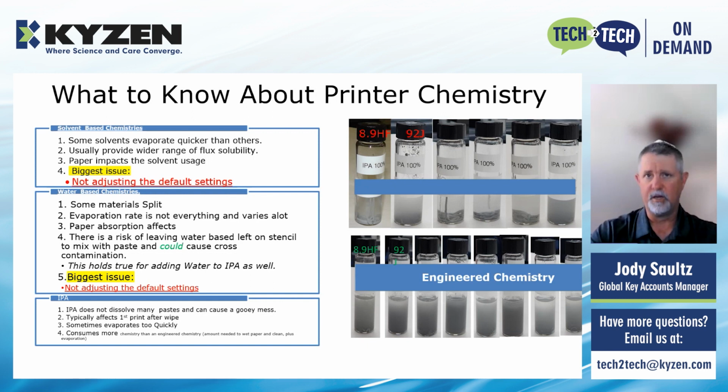So many times I hear customers say, "Oh, we mix water with the IPA." That's probably worse than running IPA at 100%, which I don't recommend anyway. And then, of course, not adjusting the default settings. The problem with IPA is that it may solubilize a few pastes, but in most cases it doesn't touch a lot of the paste, especially with the new pastes that are coming out with today's technology.